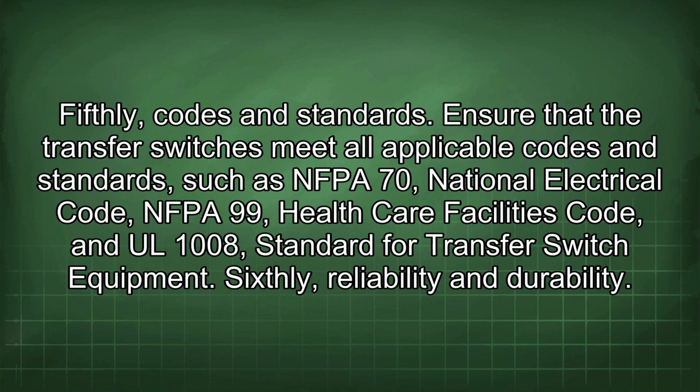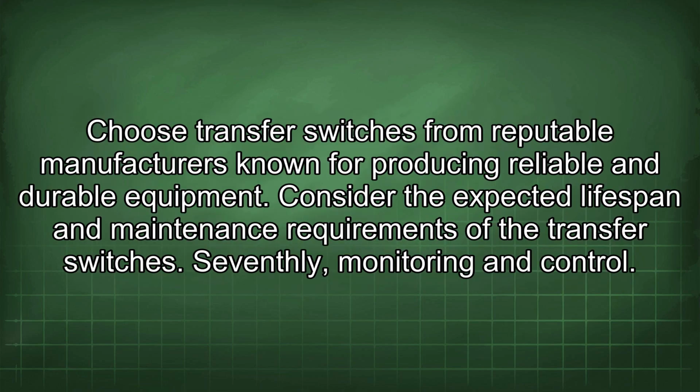Ensure that the transfer switches meet all applicable codes and standards such as NFPA 70, National Electrical Code, NFPA 99, Healthcare Facilities Code, and UL 1008, Standard for Transfer Switch Equipment. Sixthly, reliability and durability. Choose transfer switches from reputable manufacturers known for producing reliable and durable equipment. Consider the expected lifespan and maintenance requirements of the transfer switches.